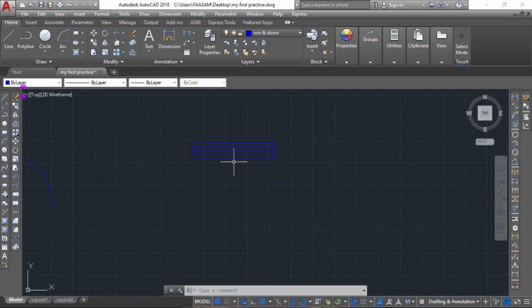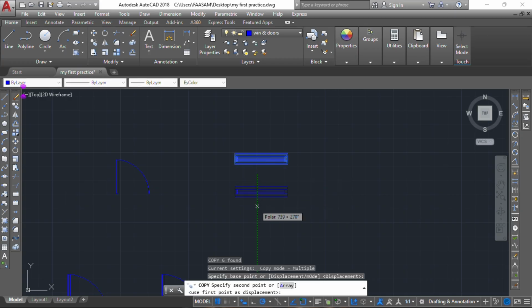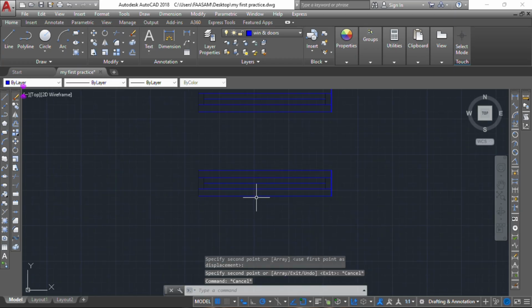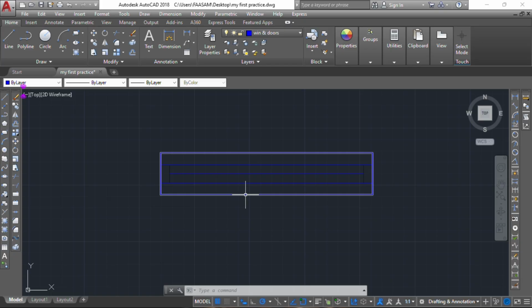Now let's create for our 600, which is our toilet window. So instead of deleting and creating another one, let's just use this. Let's copy it and bring it down. So now let's edit this to give us our 600. This is 1 2, right? The length from here to here is 1 2. So we need to reduce it 300 from the right, 300 from the left also, to get 600, right?